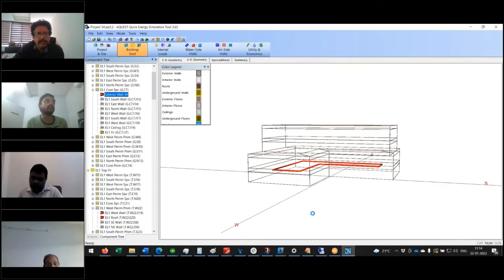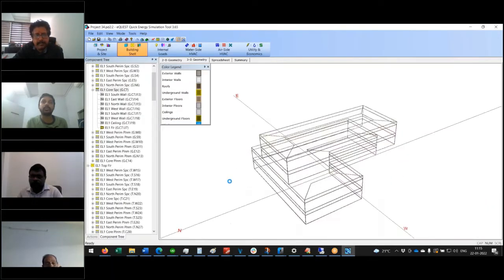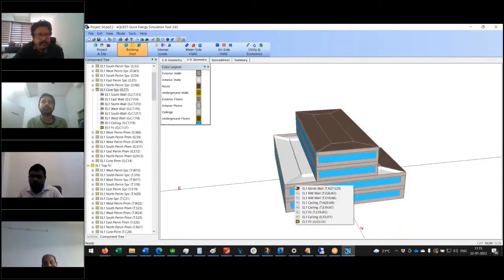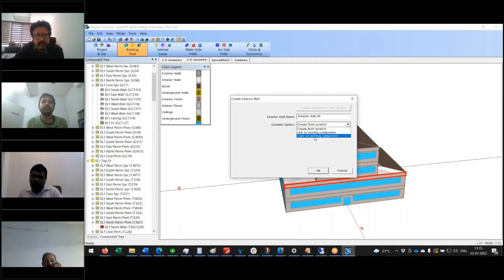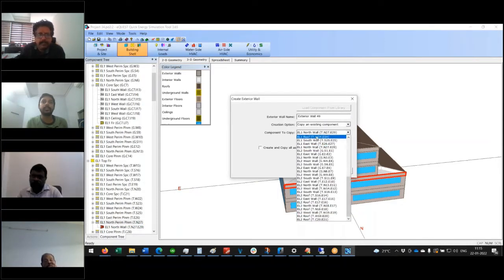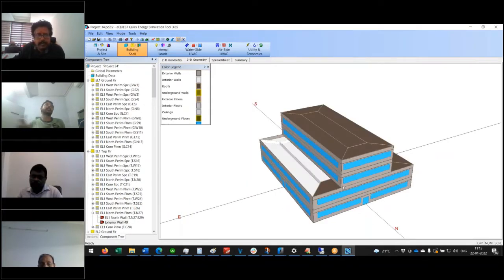Do you see the red one? That is where the roof has been created. So I'll probably delete this because we went to the wrong floor. We want to create it in the plenum zone for this one. So create it here. As a wall, I'll copy a roof, and that's it. So you can see the roof is.